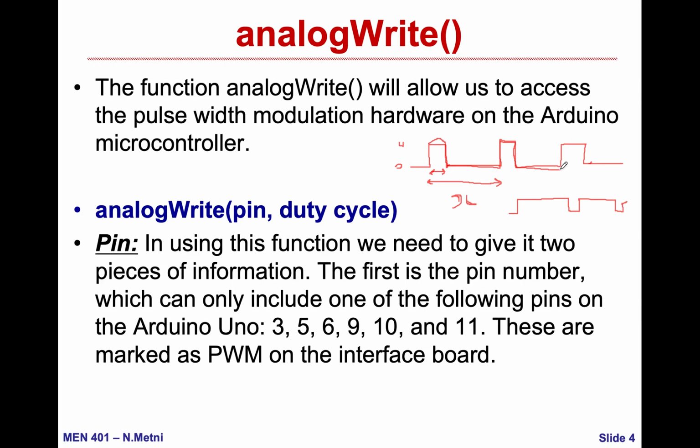The advantage is that I can specify the duty cycle I want and the frequency I want. However, the drawback of such a method, which I call a low-tech PWM method, is that I am just keeping the CPU busy outputting a PWM, which is not very practical.